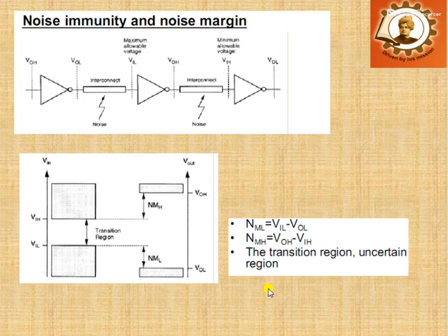So your inverter, or any electronic circuit, will be confused in predicting logic 0 and logic 1. In this figure, the shaded region shows the input and output voltage levels. So this noise margin is very important while designing any inverter.